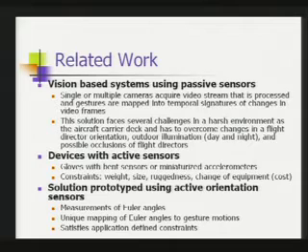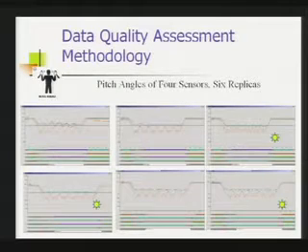We looked at the devices with active sensors. There are devices like gloves with bend sensors or miniaturized accelerometers. And again, the constraints are that it cannot be very heavy because these people are there for 14 hours, and it has to be rugged and so forth. So eventually, we decided to go with small sensors that report Euler angles, which are yaw, pitch, and roll. And then there is a unique mapping between Euler angles and gesture motions. And it was satisfying all the application requirements.